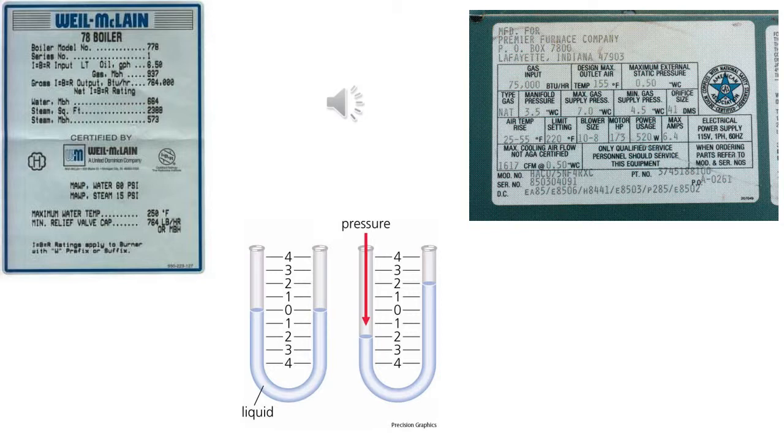A U-tube manometer is the simplest form of a manometer. A manometer is what is used to read inches of water column. Looking at the pictures of the manometer, you will notice the one on the left is filled evenly with water. The manometer on the right shows what happens when you are reading pressure. The manometer in the picture has a reading of 4 inches of water column. You add the numbers above and below the zero to get your reading.